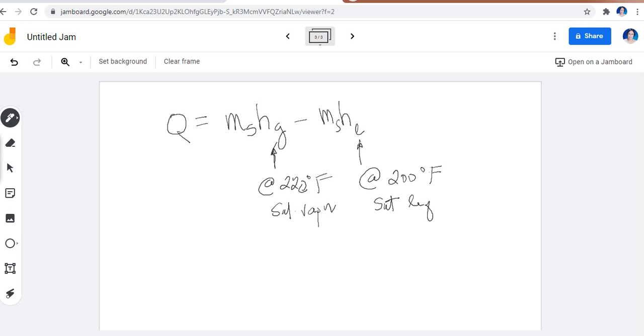So there is sensible heat and there is latent heat due to the change of phase. These two, when summed up, will be equated to the amount of the total load that your heating coil should service, or its duty to give to the air water vapor mixture. So this is the load of your coil.